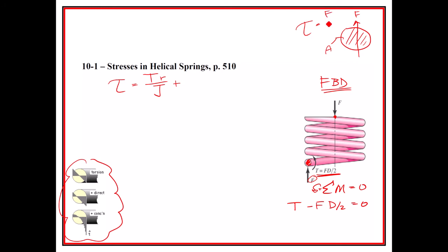Now, we know that for transverse shear we often would use a certain factor. We would put 4/3, I think, for a circle. I believe it's 4/3 for a circle, but let's just treat it as 1. Let's just say it's going to have those two things on top of it. So this is torsional. And this we could call direct shear, which we usually do F over A for. And down here, someone has made a little diagram and shown that when you add these two things together, on the inside surface right here, the torsional shear and the direct shear add together.